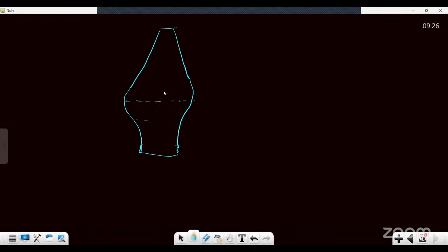Now, the dead man zone, it is the coke in the dead man zone. It is going to be something like this. So, it is a stagnant coke portion. Stagnant means whatever coke you have charged, a part of it is going to be like this. This coke will not take part in the reduction reaction. But though they will not take part in the reduction reaction, they are very, very important.